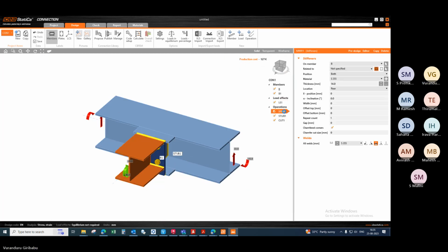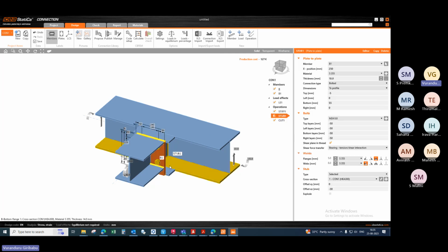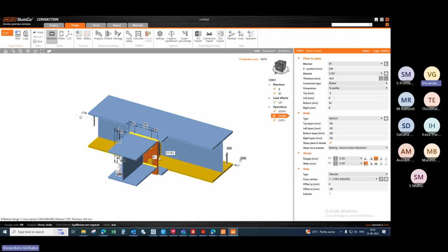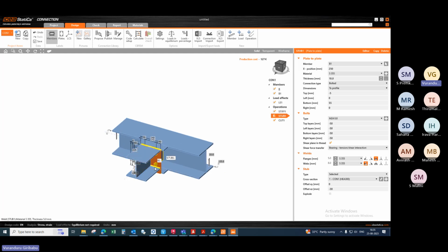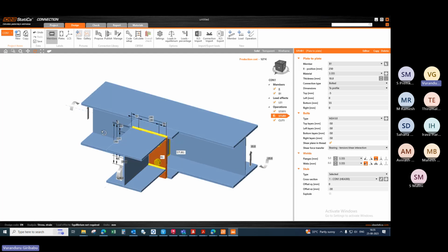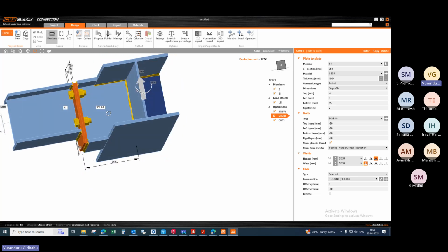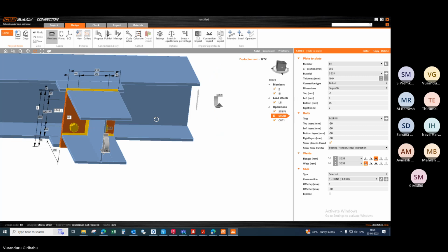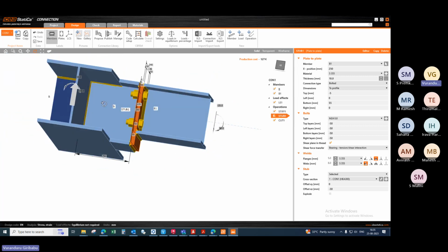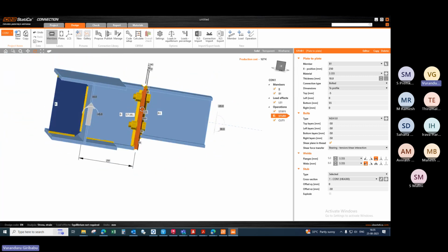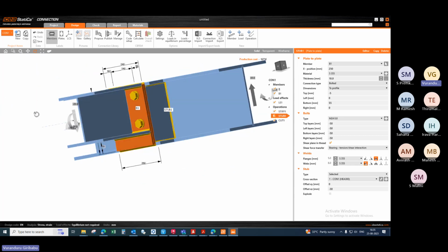Okay, then what are the operations required? This one is for stiffener one. For stiffener one, it is the same operation that we explained in the column position. Then go to stub. This stub operation is where we are making a stub connecting to the member. They are calling it a stub because it is like a splice connection between beam to beam. It's not like a complete connection.